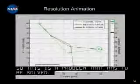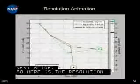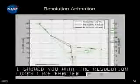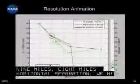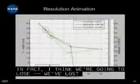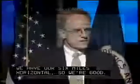So here's the resolution. Why don't you go ahead and play that? I showed you what the resolution looked like earlier. So we turn the aircraft on the right. We turn him behind the red aircraft, and you can see that we've got 9 miles, 8 miles horizontal separation. We've still got vertical separation. In fact, I think we're going to lose it. Okay, we've lost vertical, but we still have our 6 miles horizontal, so we're good. So the separation criteria, remember, is 5 miles or 1,000 feet.